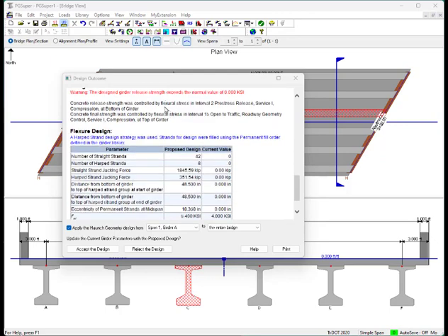Again, we've exceeded the max normal value of 6 KSI, which is unacceptable. So here's an example of a design that works, but it's not acceptable for our needs because of the high required release strength. So at this point, we could choose a larger girder. But our fake bridge is crossing a fake railway, and a deeper girder would cause clearance problems. So we need to work with what we have.